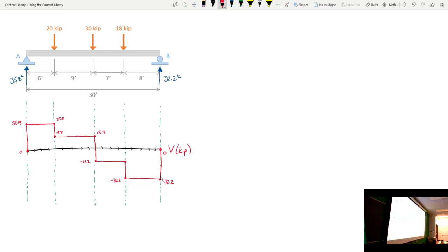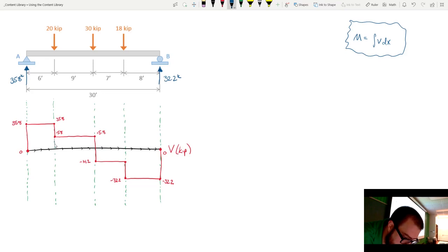I remember a little conclusion that I had made a little bit ago that said that to determine the moment diagram, I need to integrate the shear diagram. But somebody made a point about what is integration? Determining the area under the curve? Do I need to break out integrals to tell me what the area of that is? Really? No, I don't. Okay, let's keep this simple. All right? I don't know about you, these are rectangles.